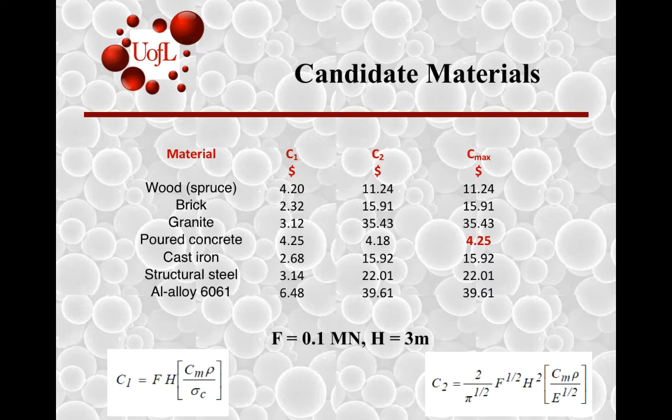In this situation, for this design, we want the material to not only at the minimum satisfy the compressive constraint, but also the buckling constraint. So we have to basically choose for any given material which of the constraints are dominant. Right? If you go cheaper than here for spruce, it will not satisfy the second constraint.